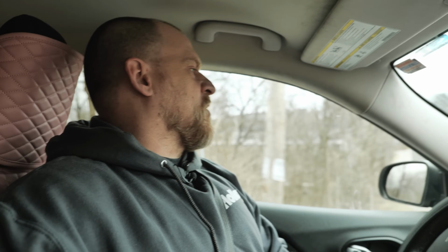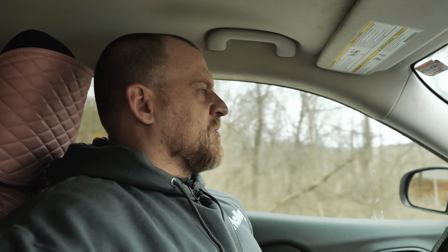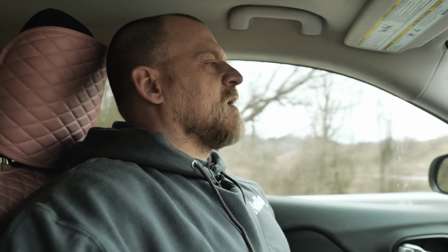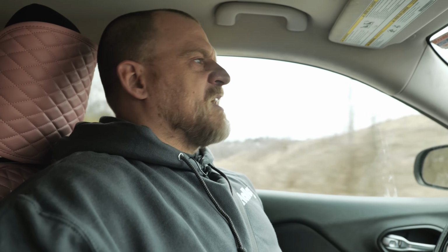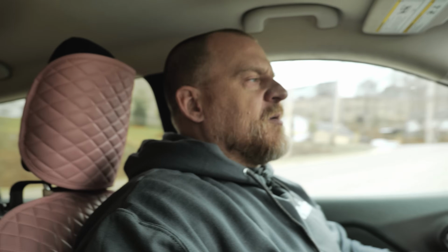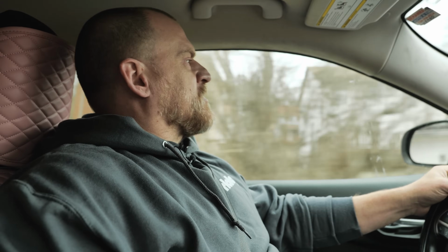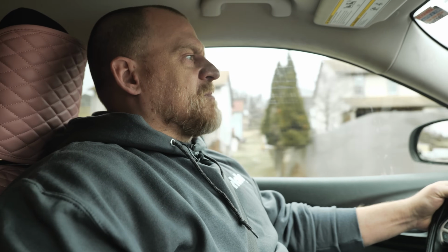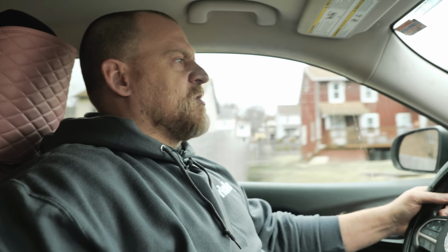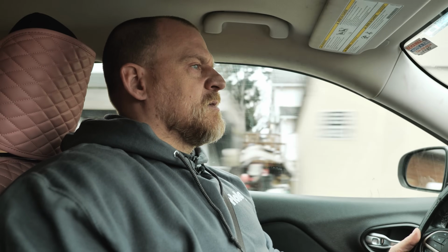There's no reason to get involved. There's no reason to measure fuel pressure, things like that, not when it's one bank. Scope and fuel injectors, ignition system, none of that's gonna be relevant, not without fault codes or direction that would put me that way. I would think too, if the oxygen sensor wires were touching ground, we would have some type of circuit fault with the O2s. We don't have that either. I don't know what's going on with this.